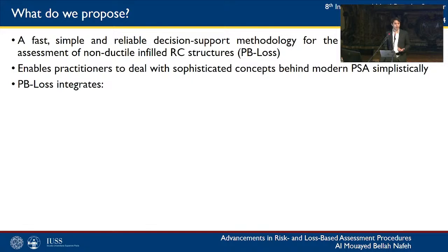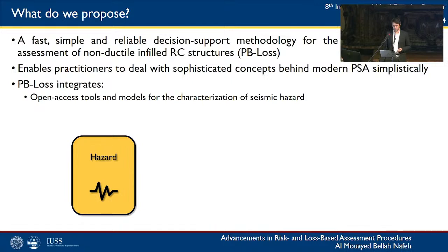Well, we propose a relatively fast and reliable method for the building-specific loss estimation of non-ductile infilled RC frame buildings, a procedure that could define the technical standards behind Sisma Bonus for this typology of buildings. The proposed methodology allows practitioners to deal with the sophisticated concepts behind modern probabilistic seismic assessment in a simplistic manner.